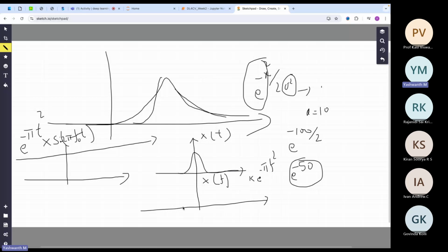Okay, so it is something like this. The sinusoid, I'll just plot the magnitude, has two impulses at f0 and minus f0. Because it is multiplication, it's convolution in the frequency domain. Impulses, when you convolve, it just shifts.